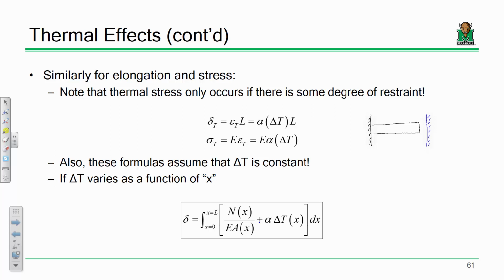So if you wanted to define the total closed form formula for deflection for axially loaded members, this would be it. This would be like the one formula that you would need to remember for axial members, period. Okay? So first off, if everything's constant, then this one just turns to PL over EA, and this just turns to alpha delta T. If you don't have any temperature load at all, this one goes to 0, and so on and so forth. So that one formula will tell you just about everything that you need to know for temperature. Everybody okay with this? All right.